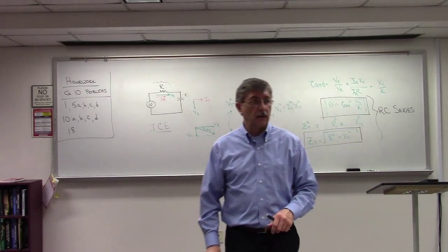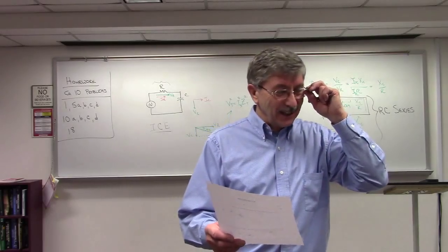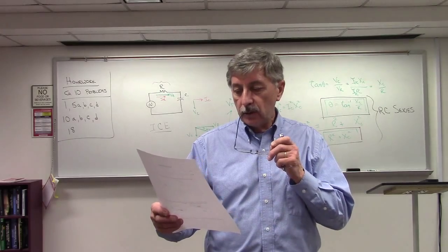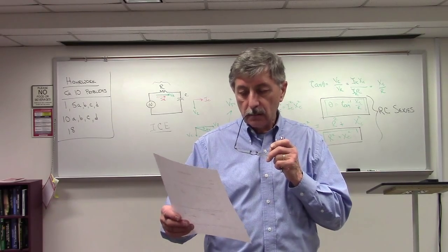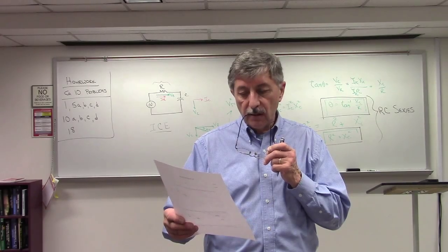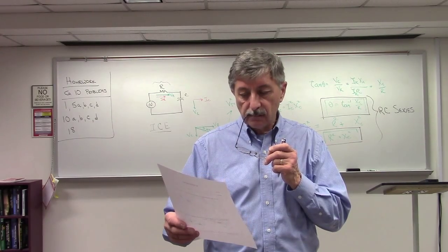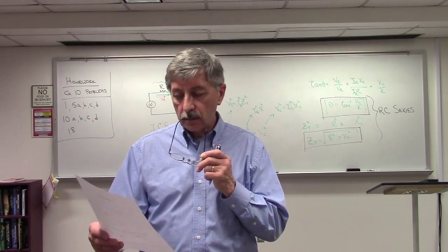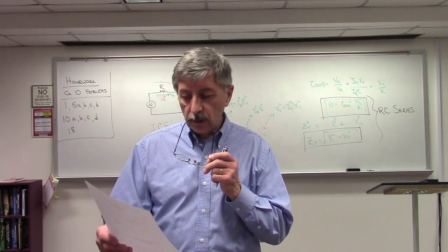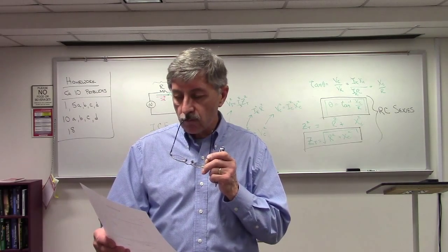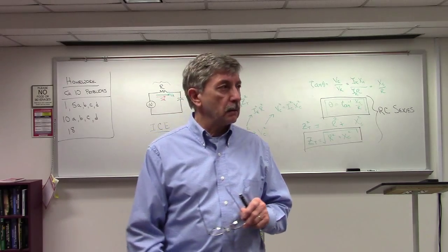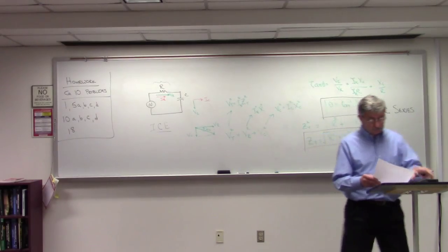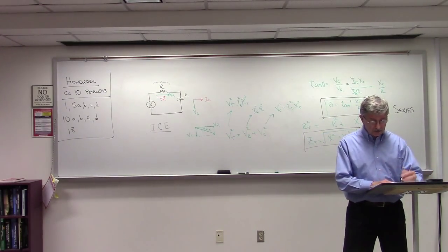Okay, one more change. Number 2 is not working out for me at 500. Change the resistor in number 2 to 1 kilohm from 10, and change the frequency from 5 kilohertz to 500 hertz. See what that does. You said change resistance to what? 1K. Lower the resistance to 1K.